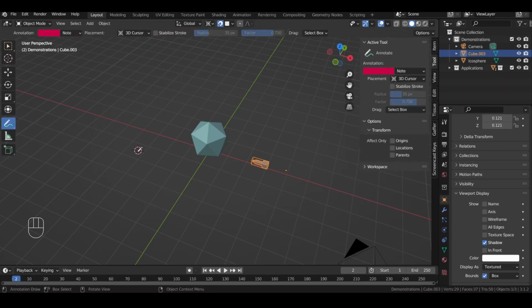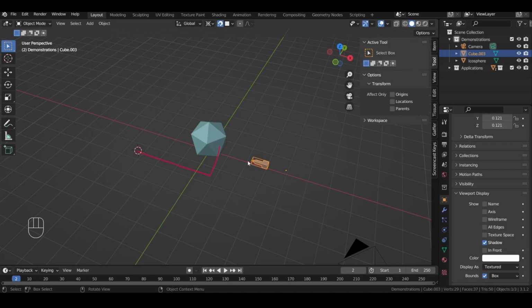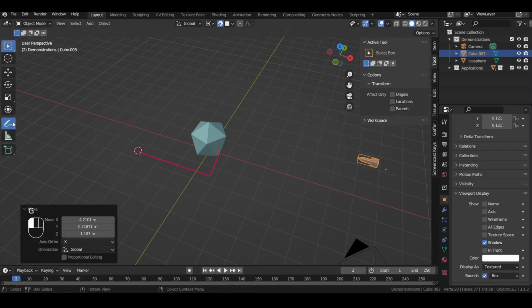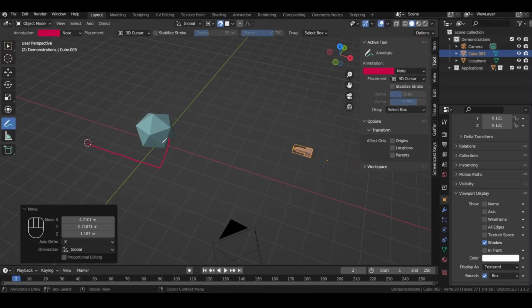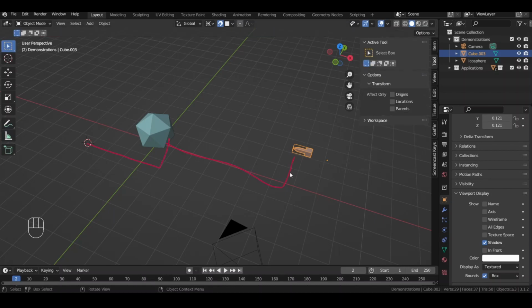And so as you can see, to snap the 3D cursor to that face, you move it down on the x-axis and a little bit on the y-axis, right? So when we go ahead and snap the object, you could see that it does a similar thing, and it moved it along the x-axis and a bit on the y-axis. The same exact translation, right?